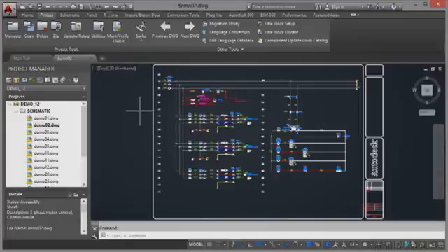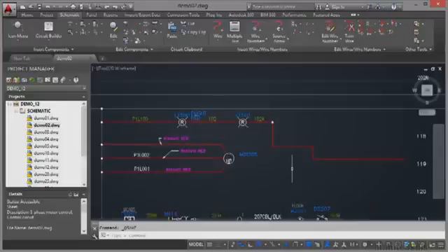Quite often in AutoCAD Electrical drawings, you want to build what they call a parent-child relationship with certain schematic components. Typical examples are a motor and then the motor starter contact that would be used to actually start the motor up in the circuit. We're staying in Demo 12 project and we're still in drawing Demo 02. Make sure that you're in your Schematic tab here on the ribbon.